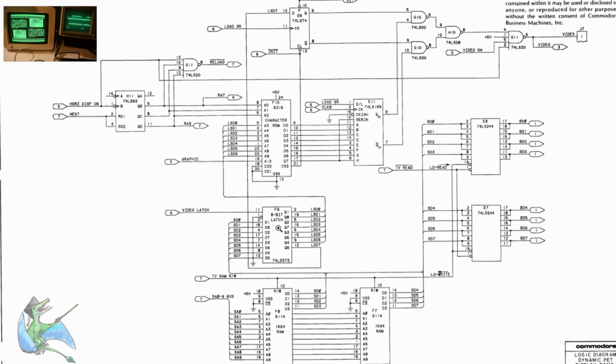So it goes in the latch. When the character is ready to be output, it immediately outputs the same value that it latched out here, and then that tells the character ROM to find the row of dots associated with that character. So if it's a letter A in here, that's on a PET, that's PETSCII code 1. So you'd have 1.